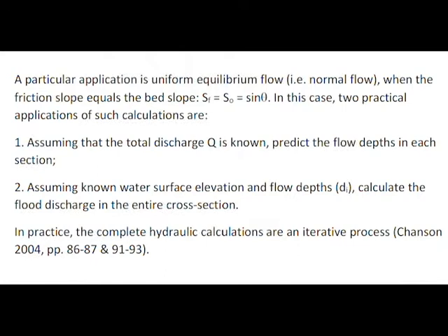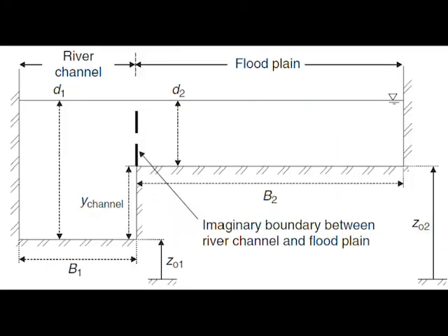In this case, two practical applications of such calculation are: knowing the discharge, let us predict the flow depth in each section, and assuming a known water surface elevation, let us calculate the flood discharge in the entire cross-section. In practice, the complete hydraulic calculations are iterative.